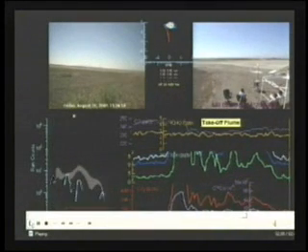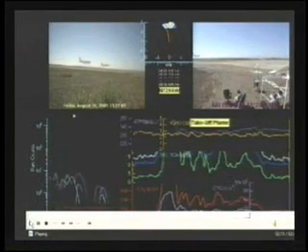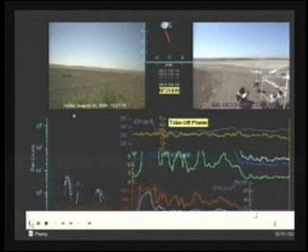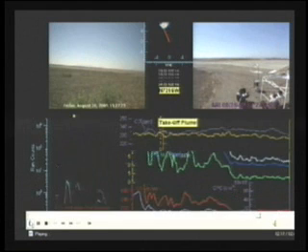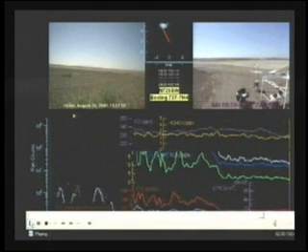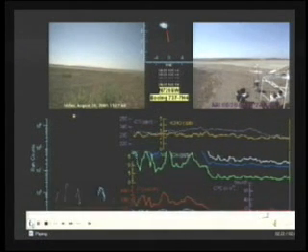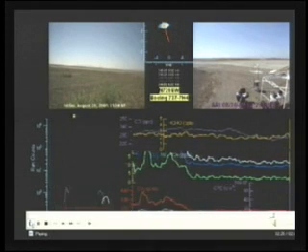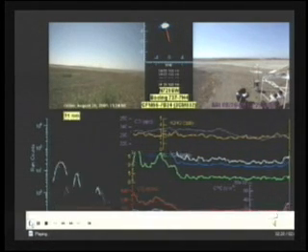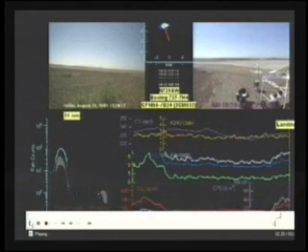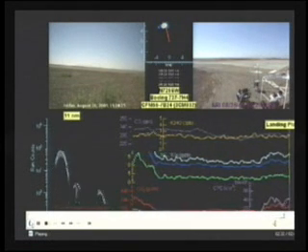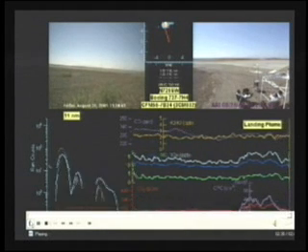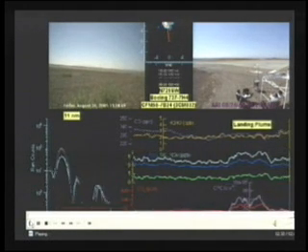The harder thing to do: when the plane was idling in front of us, we could get a tail number. When the plane was landing, it was much harder to get a tail number. But we used binoculars and tried to scan it as we went by. This was a different airplane, but it also had CFM56 engines. That was the most common engine at that airport. And now you can see that we have operating conditions that are higher than idle because we have very few hydrocarbons, but we still have some NOx, but not as much NOx as we would expect for a takeoff condition.